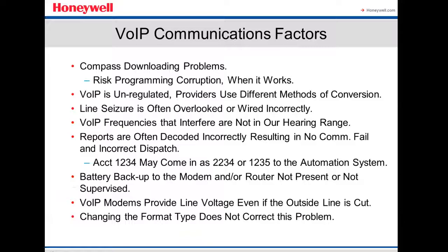So that's why we don't recommend using this. It could work 1 day, 2 days, but eventually it's going to start giving you a lot of problems. So we don't use voice over IP communication for these 3 panels. In general, for all VISTA panels, we don't recommend voice over IP communication. VoIP frequencies are not the same as analog, which is why it sends the wrong signals most of the time.